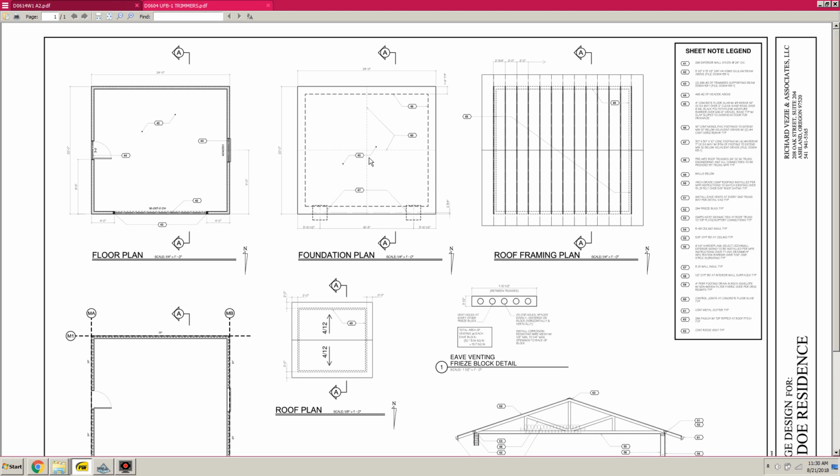We're now on DCAD lesson 18D, and we're continuing with project evaluation. In our last lesson, as far as the large garage door header was concerned, we looked at both the loading from floor joists, which we're going to run in the long direction, and also the feasibility of utilizing this existing 13.5 inch by 5.5 inch glulam beam. Both the joist system running in the long axis and the beam will work for our new application. This beam will now in effect be a floor beam.